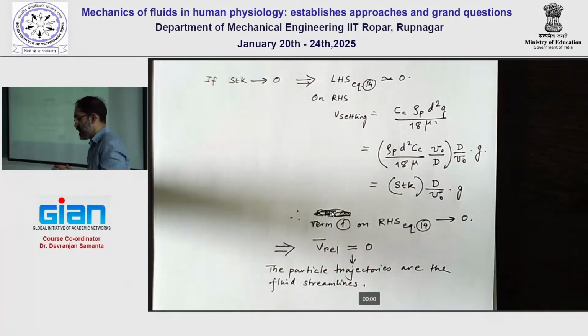Now whether the rho p can balance the squared growth of the D is a good question. Even for a 2 micron or 1 micron particle, because of that small d, there is always a huge impact on the Stokes number getting much smaller. Whether the rho p being 1100 kg per cubic meter rather than 1000 kg per cubic meter is enough to balance that effect is a good question. The consideration that you showed are the typical ones, so there won't be much of a difference.